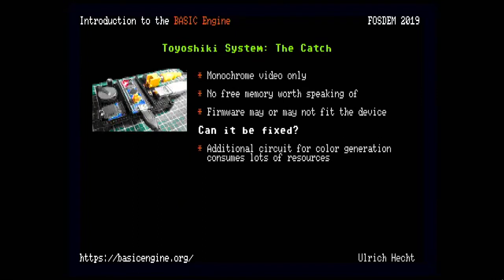The obvious ones are it consumes a lot of hardware and needs all these timers. You don't have timers for your system anymore, so you have to do a lot of stuff that would be way easier otherwise. But the way more important thing, which I only thought of once it was almost finished, is that color graphics need more memory, and we don't have that. So if you have like 8 colors, 3 bits, that uses 3 times as much memory as the monochrome graphics, which leaves you with nothing left.